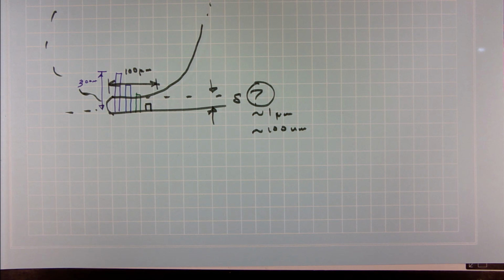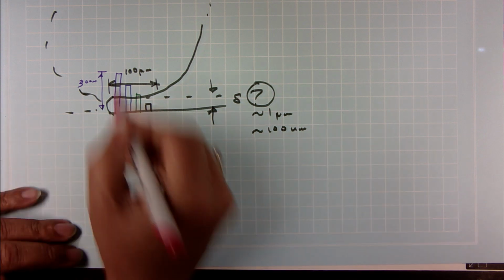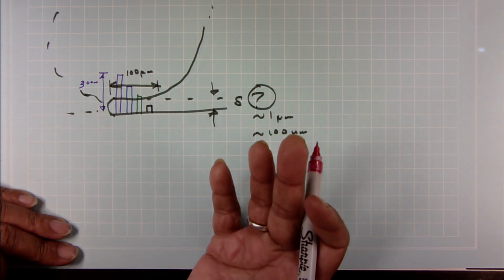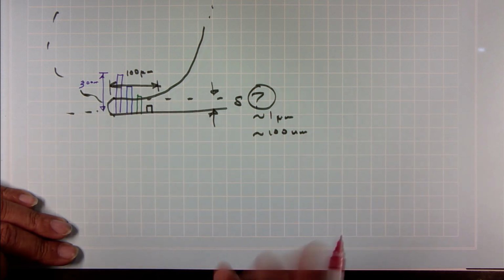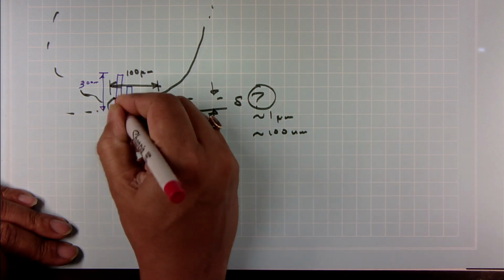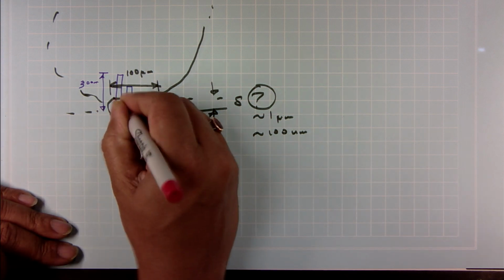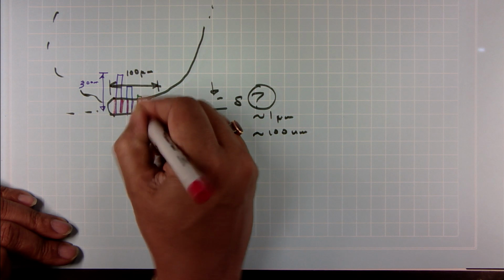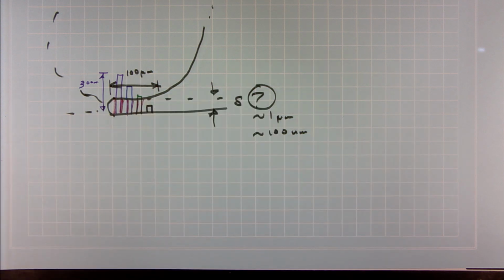Okay. So, that means the part that is sticking in the vapor is not really conducting any heat, because vapor is almost an insulator. So, where is the heat getting conducted? It is only getting conducted here and here, is it not? It is getting conducted here and here. So, as long as that fin height is more than 100 nanometers, the rest of the height does not matter. So, that tells you that the micro layer thickness has to be of the order of 100 nanometers.